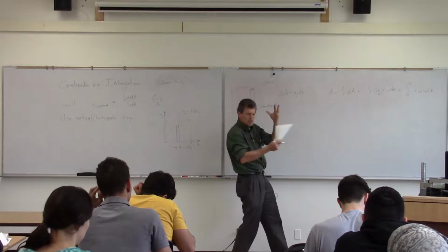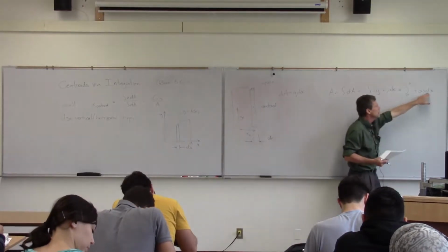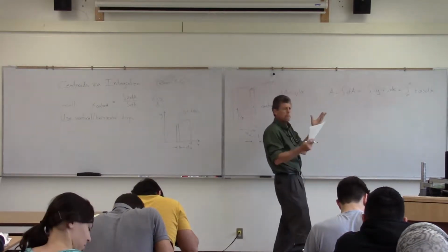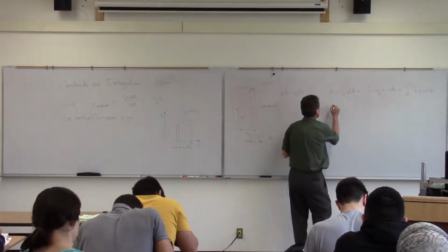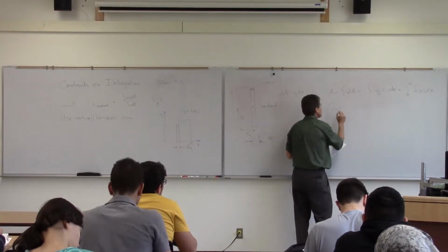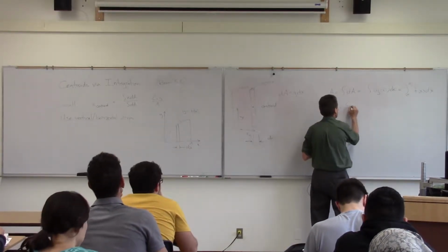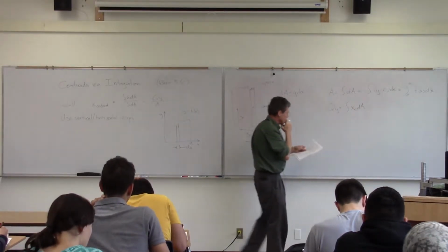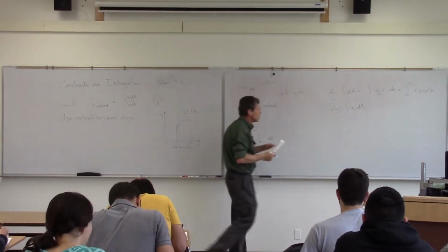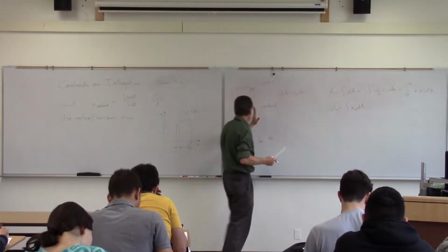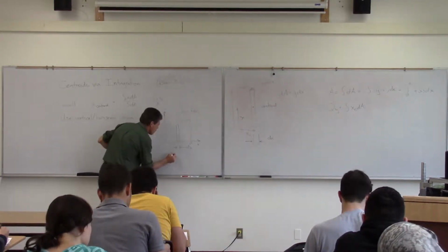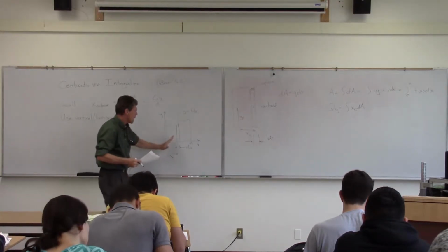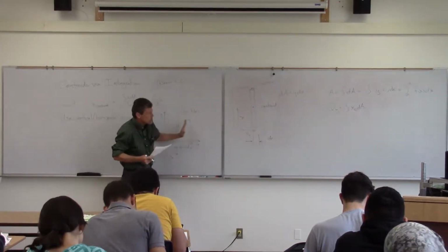I have an f(x), so it's going to be x squared, x cubed, something like that, dx. And basically, at that point in time, I go back to my calculus book and say, well, I can figure that one out. And then we'll do the same thing with those first moments of area. And remember, the first moments of area basically have this moment arm. So we've got this area here, but now we're going to recognize the fact that it's got this moment arm now, and as I move along there, it moves away, so that x is going to increase.